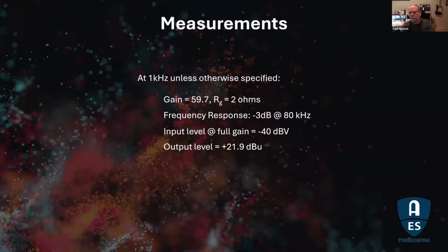So you can take a value that's in dBV, and you can convert it to dBu by adding that magic number. And so you see plus 22 dBu is about plus 20 dBV. So I'm sorry if that's confusing.